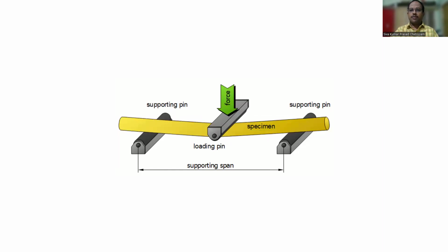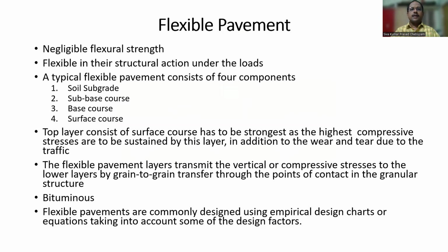Now let us first talk about flexible pavements. The reason we have discussed this concept is because flexible pavements typically have very little flexural strength, and in their structural action, the only structural action of flexible pavements takes place exactly under the load of a wheel.